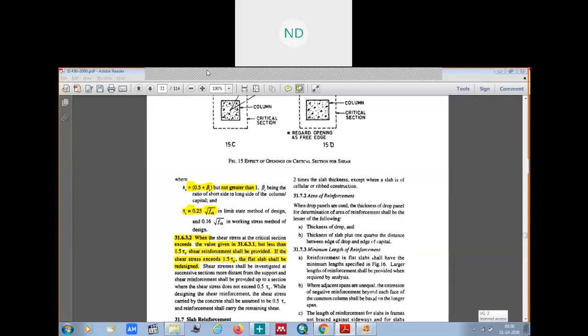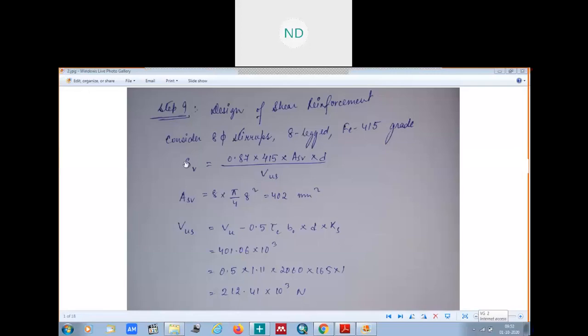Now if we see, these are the stirrups. That means we have to provide shear reinforcement, and shear reinforcement is nothing but the stirrups we will provide. When we have to provide shear reinforcement, we provide extra stirrups there for resisting the shear, after checking the shear.